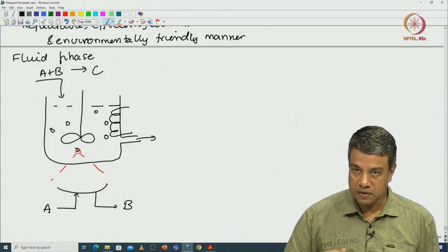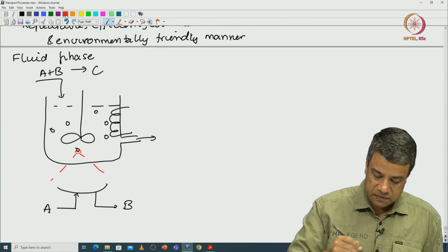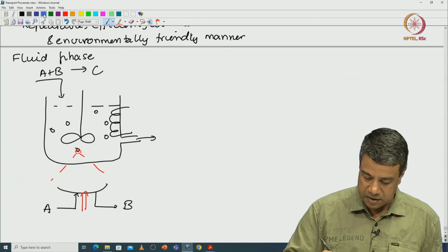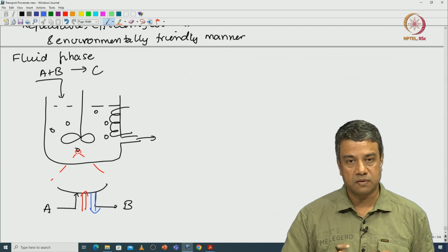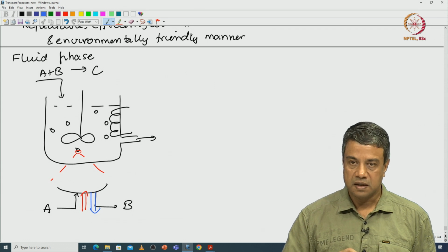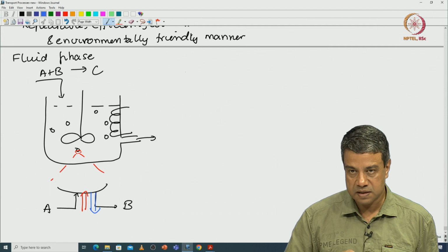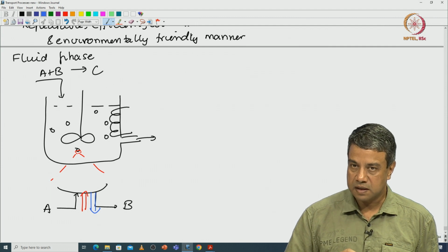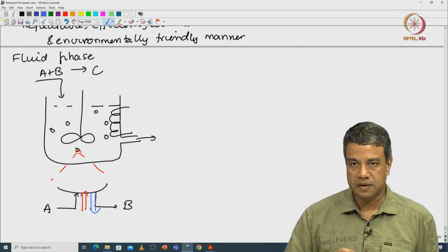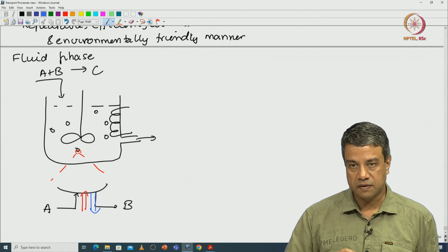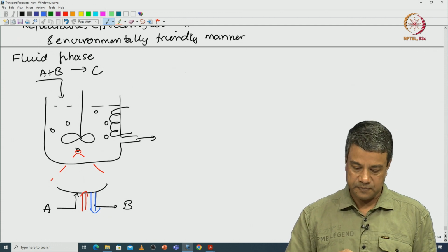It is not enough to add heat in the heating coils. That heat also has to be transferred through conduction, either to the surface in the case of an endothermic reaction, or away from the surface due to an exothermic reaction. If the heat is not transported in the correct quantities, then for an endothermic reaction the reaction rates will fall because the material will cool. If it is exothermic and the heat is not removed from the surface, then you could get runaway reactions.